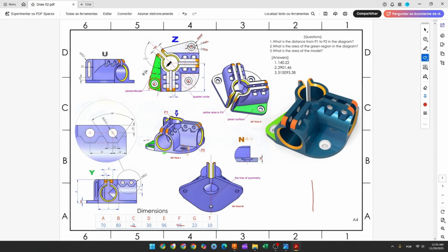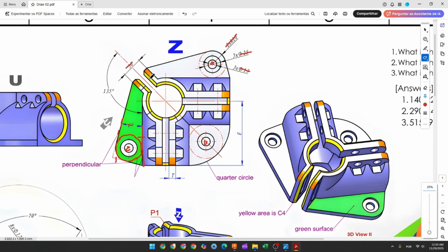Now we will make the center pipe here. So we will select the top face and make a circle here with 70 millimeters of diameter and create these 2 lines here. We'll make the cut later, okay? So no problem. Just make this sketch.